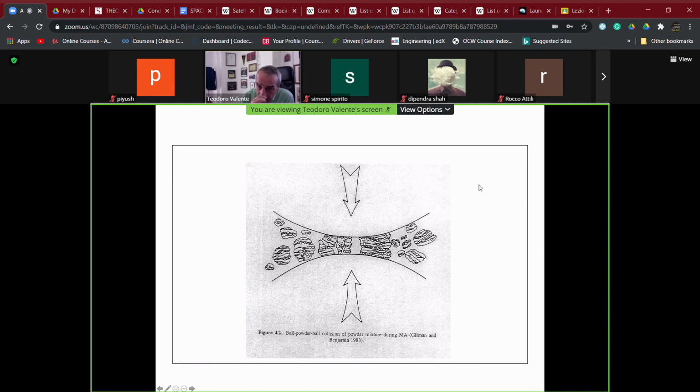And this can allow us, for example, also to have nano-sized oxide particles dispersed inside a metallic matrix, which is nano or submicron. But that means, as we said some time ago, less than 100 nanometers or less than more or less 500 nanometers, which represent the starting point for obtaining suitable ODS powders, materials which can then be consolidated.